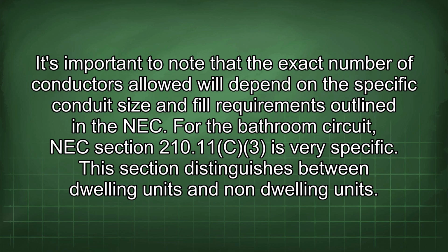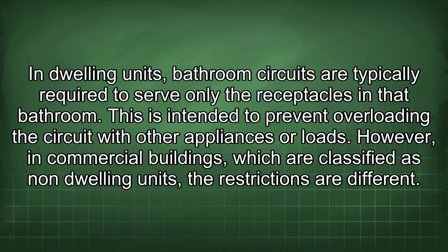For the bathroom circuit, NEC section 210.11c3 is very specific. This section distinguishes between dwelling units and non-dwelling units. In dwelling units, bathroom circuits are typically required to serve only the receptacles in that bathroom. This is intended to prevent overloading the circuit with other appliances or loads.